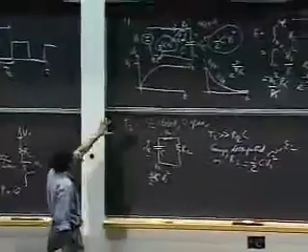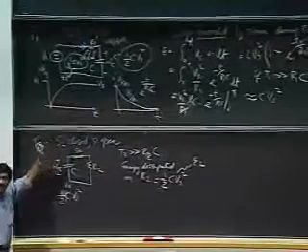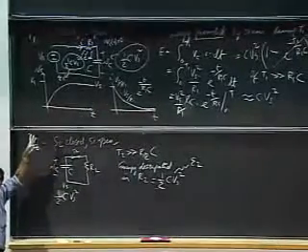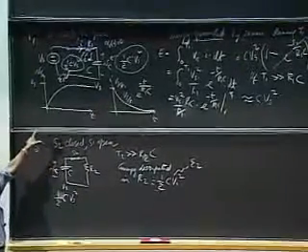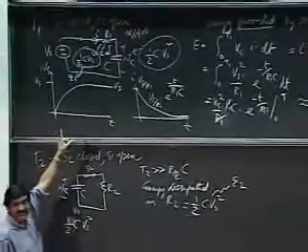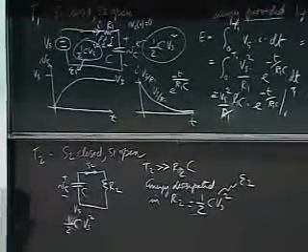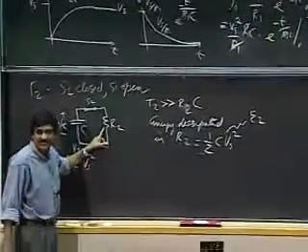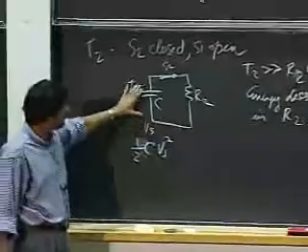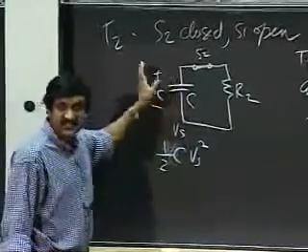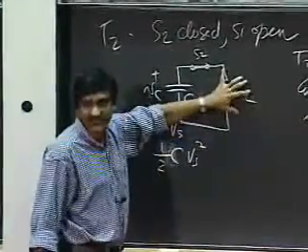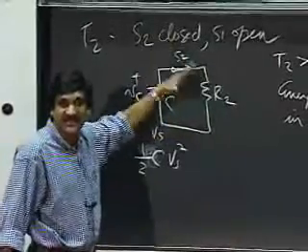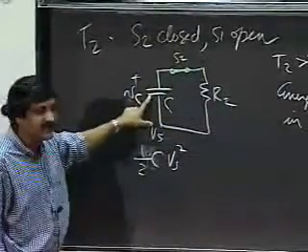If the time constant is small enough compared to the time that I charge the capacitor, then half the energy gets lost in the resistor, and that is simply half CVs squared. And if I let this discharge completely, it doesn't matter what resistor I'm discharging it through. That's the intuition. If I have certain energy here, and I let it discharge completely, it doesn't matter what this resistor is. Small or large, all this energy gets dissipated there.